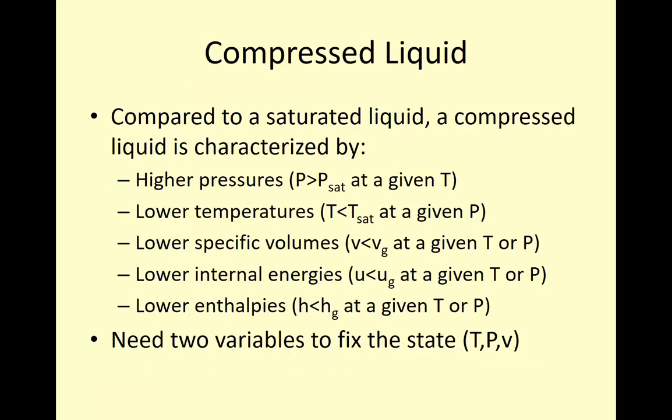All right, so now let's look at the compressed liquid region. If we're looking at the dome, this is a superheated vapor, this is a saturated liquid-vapor mixture, and this is a compressed liquid in these states. The pressure line on a T-v diagram is something like that. So: superheated, saturated liquid-vapor mixture, and compressed liquid. Compressed liquid is also just liquid water, which is what we are familiar with.